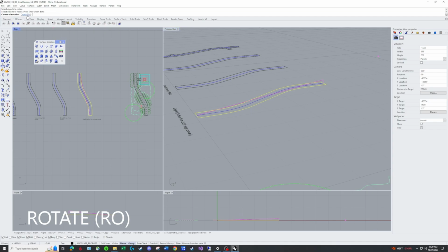Okay, good. I want to make sure I copy this because I want to keep my 2D line work in place. The 3D rotation is kind of interesting. I want to rotate it from here. I want to rotate it from this point up to that point. Well, when you select in 3D, you see what it's doing. It's just putting a flat surface down. And if I chose it, I'll go ahead and do this real quick. See, it's only just going to rotate this way. It doesn't want to operate vertically. We can use the command rotate 3D, but it's kind of difficult sometimes to operate that command.